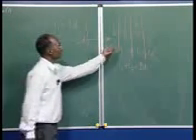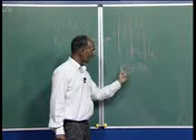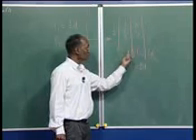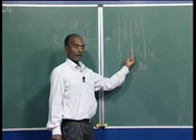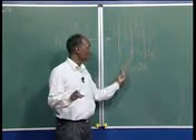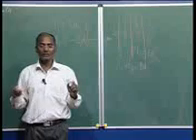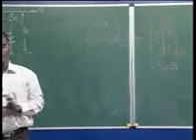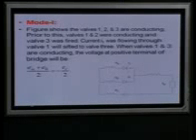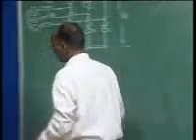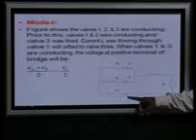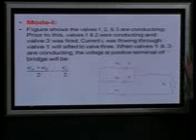So, in this period when the 3 valves are conducting, the current I1 and I3, because current shifts from here, which was earlier at this point ID, now it is going to be 0 here, means I1, and I3, which was 0 here, now it is going to take the complete current of the DC link, that is ID. So, that is why in this period it is always I1 plus I3 is equal to ID, because we assume the DC current is constant in this link. Now, this is the case when, before that, 1 and 2 were conducting and 3 got the pulse and it is now conducting.